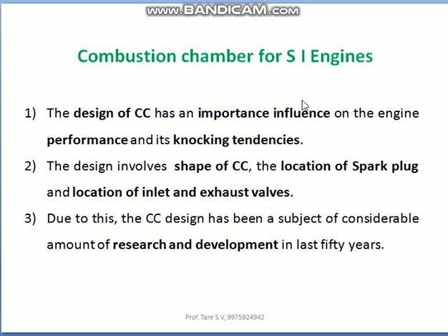The design of combustion chamber has a very important influence on the engine performance and its knocking tendencies. This design involves the shape of combustion chamber, the location of spark plug, and location of inlet and exhaust valves.